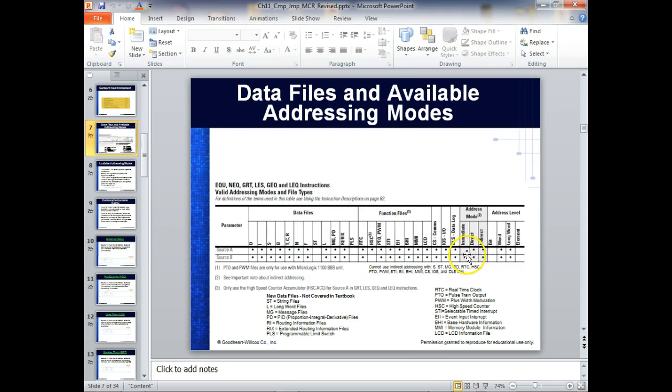These are addressing modes. We'll get into these. The ones we've been using so far are immediate and direct. Everybody okay on those addressing modes? Immediate is where we deal with constants, right? That means the actual operand is part of the instruction itself. Direct means we give the direction to where the operand is located, so this is when we specify one of our registers.